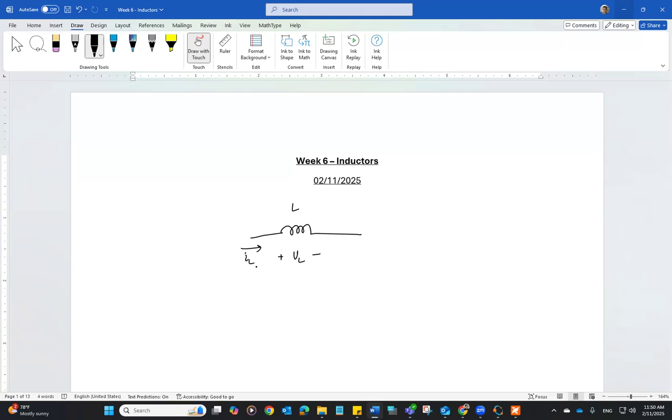If you have an inductor in a circuit that you are exciting with a DC source, then when you start the DC source, current starts passing through the inductor, a magnetic field is established, and the energy is stored in that magnetic field. Initially this magnetic field is changing, and as long as it is changing, a voltage is induced across the inductor.